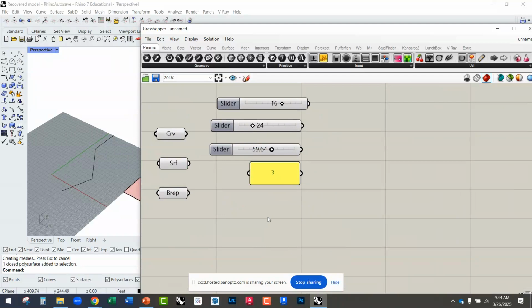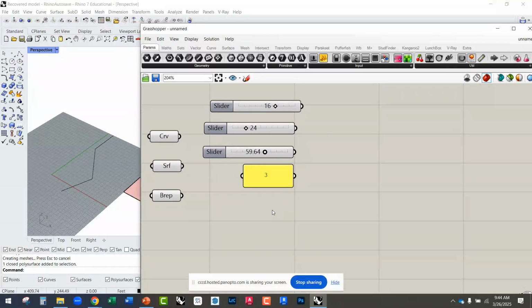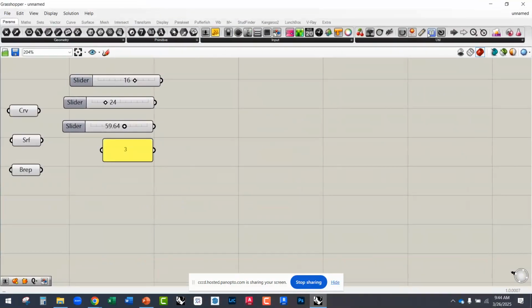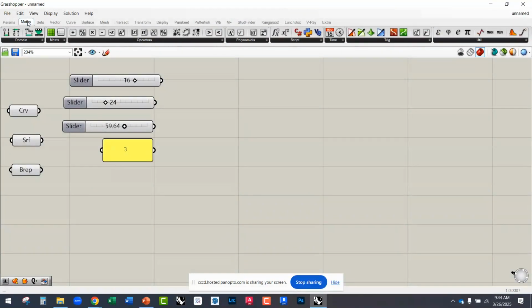Grasshopper also starts counting. So any list, it starts counting at 0. So if it shows you 0 through 10, there's actually going to be 11 numbers in that, right? Because it's including 0. So just keep that in mind when you're working. I'm not going to go into everything here. I think just the basics of what we need to get started.